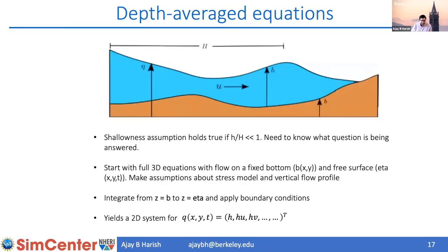Just to give an idea of the shallow water assumption: the ratio of the depth of the water to the wavelength is much smaller than 1, and we can use some kind of approximation to ensure that the shallowness is satisfied. But as these waves propagate and come near the coast, the depth starts to decrease, which means the energy has to go somewhere. So the amplitude of the wave starts to increase while the wavelength starts to decrease as they near the coast.